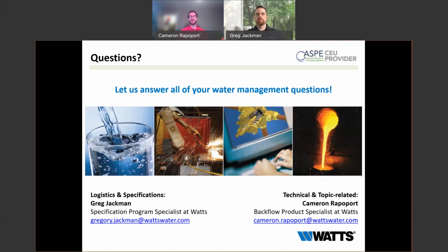But the relief valve, because it's not manually operated on an RPZ, it can open because of pressure fluctuations, or even if you have a leaky first check and you haven't noticed, right? And there's a water main break. That relief valve is going to be open.